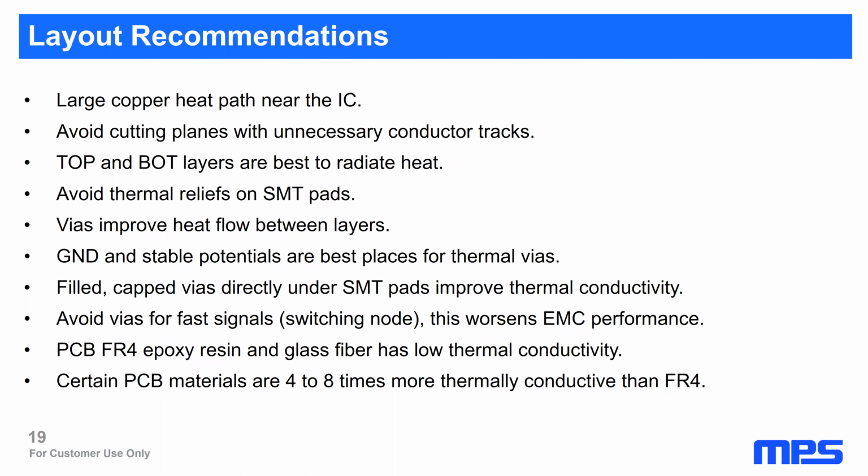This means bring the copper as close as possible to the IC, and don't think the PCB will help you much. If there is not much copper on the top layer of the PCB and you don't have thermal vias, the big PCB helps you not much because the thermal conductivity of epoxy is bad.